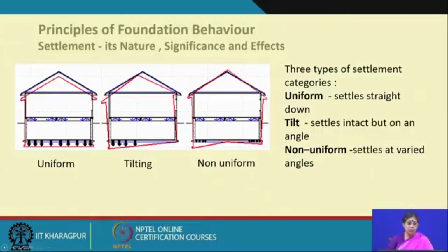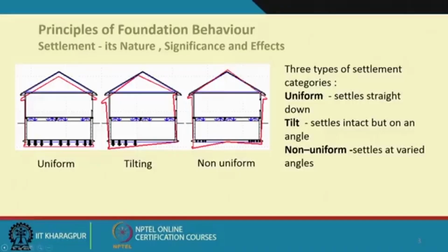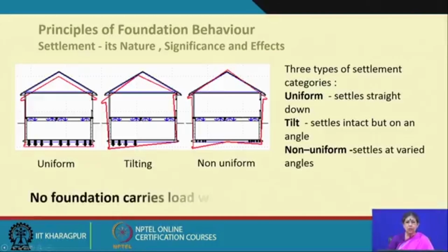In the case of York Minster, it was that differential settlement which was diagnosed as the major cause. It is also important to know that no foundation carries load without settling. There will be some settlement, but not all settlement is dangerous, because there will be some adjustment. With uniform and tilting settlement, generally there is not much of a problem. The problem is the non-uniform settlement, which is manifested in cracks, and if that continues, as we have seen in York Minster, then it is very important that some measure is taken to prevent that.